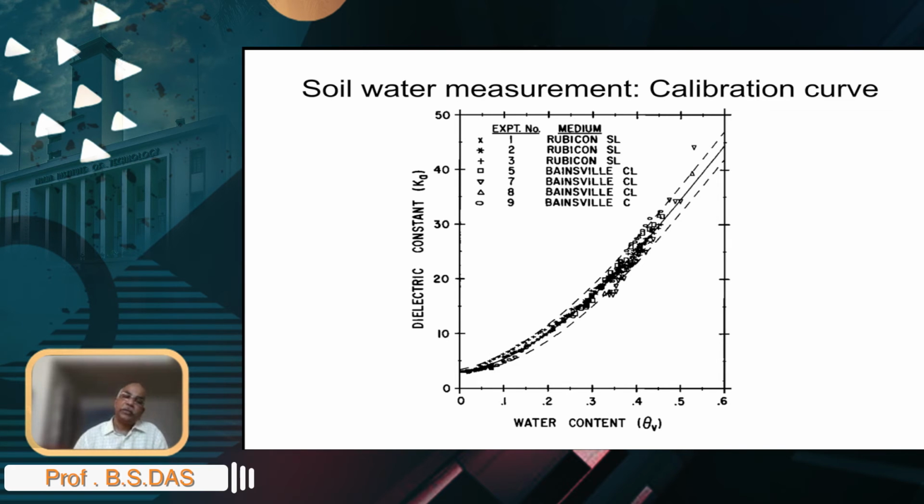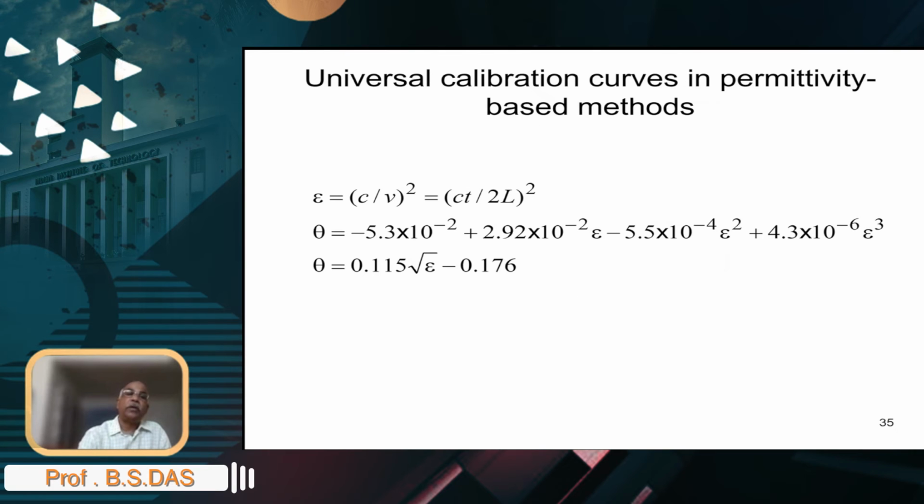is unique. And so these sort of measurements in the 70s really led to development of soil moisture sensors based on the measurement of the dielectric constant, where you can have a simple, maybe polynomial form of the equation, or some kind of a power form of the equation, relationship between the volumetric water content and the dielectric constant.